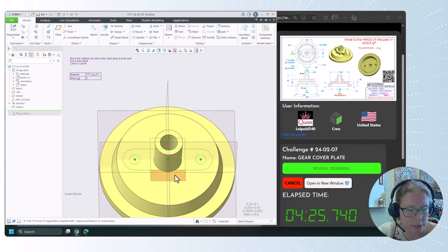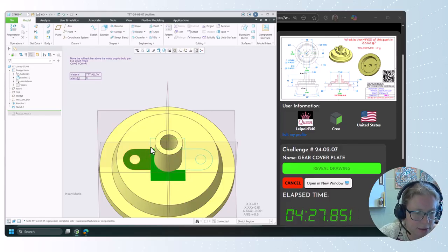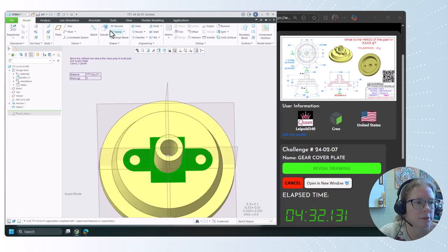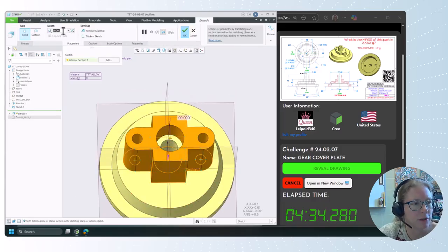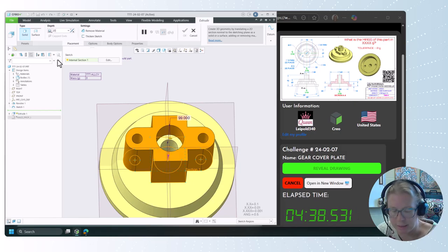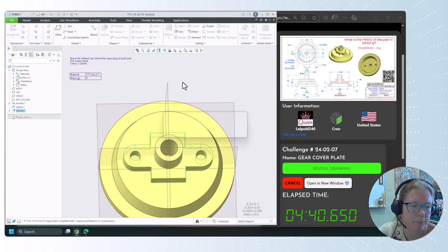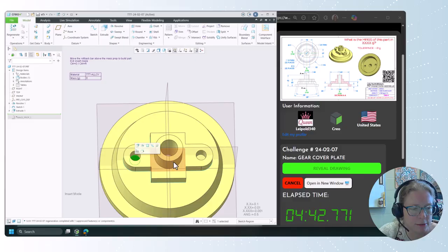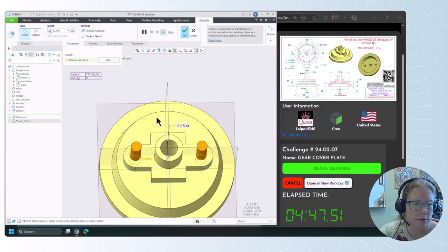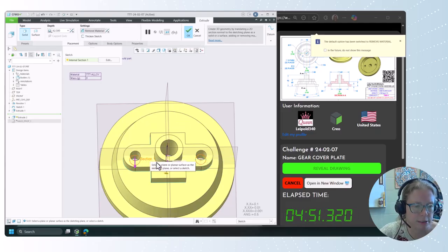And on sketch region, we're going to take this and here and here and here and here and here. That looks good. We'll extrude those up for a height of 60 is where they get to. They start at 40, so that's a height of 20. I'm going to use that same little whole sketch region there and extrude the other direction. There we go. They're removing material.